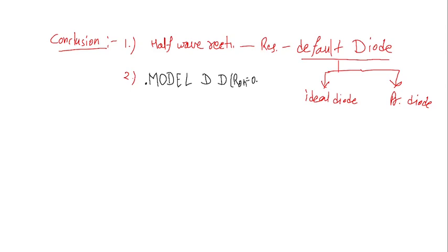You can write it, for my case I have used 0.1 milliohm, space, and off resistance 100 mega ohm will be here.